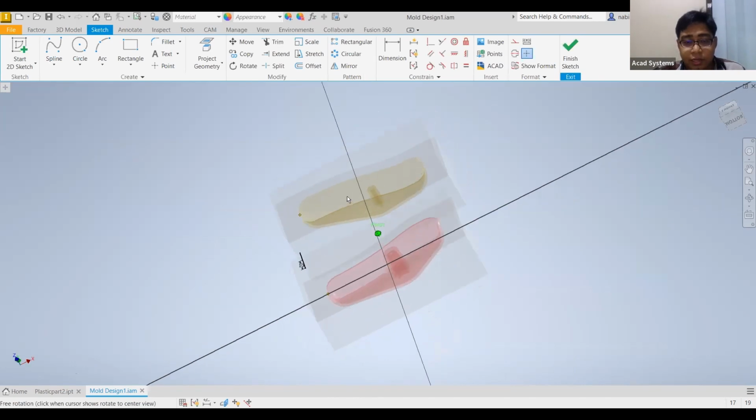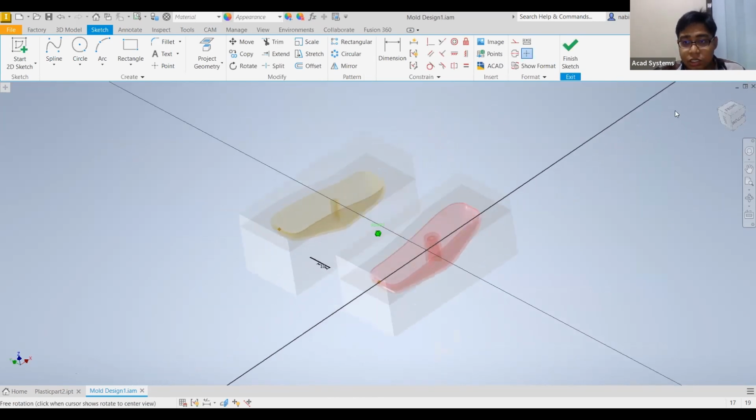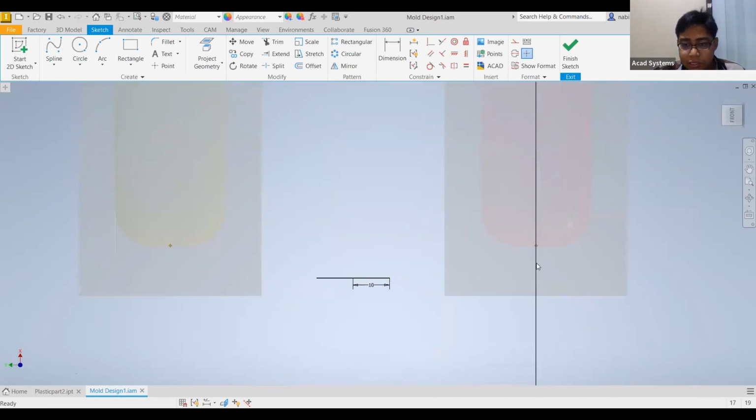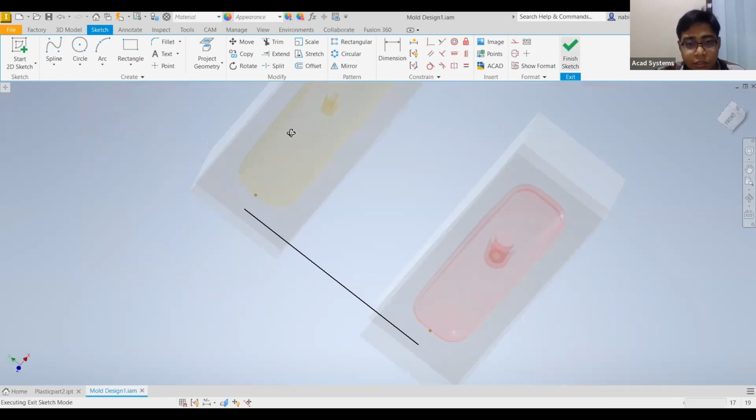So this is where I can enlarge this runner sketch, just to make sure that the endpoints reach the end of this gate. So I can just re-enter the value. Let's say I'm going to go with 50, but it should be close to the area now. And I can hit finish sketch.